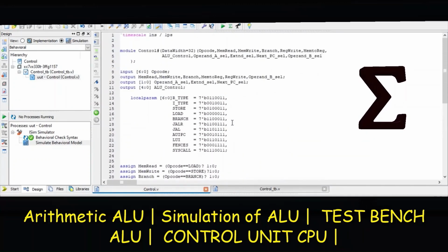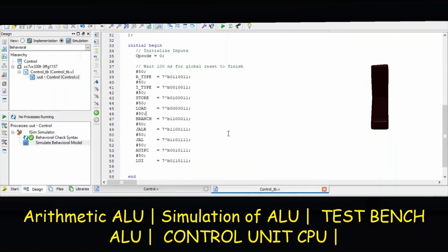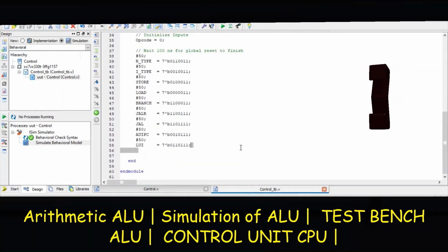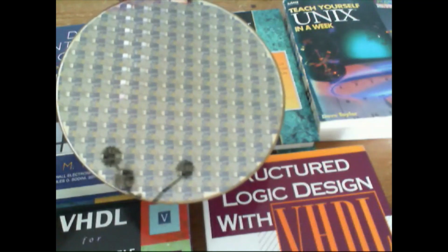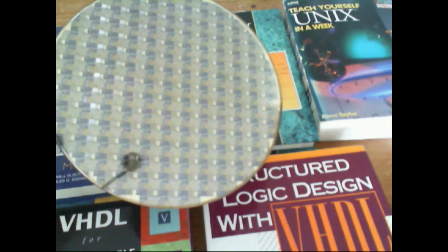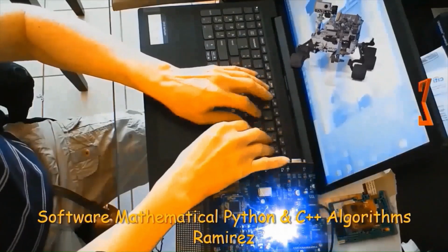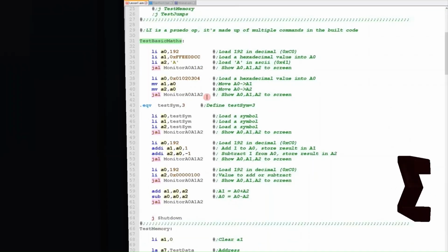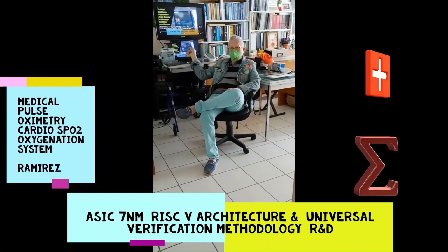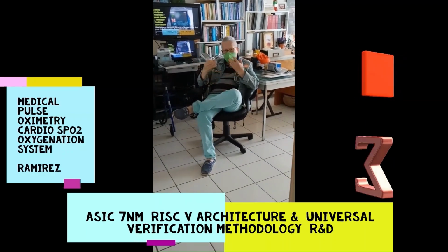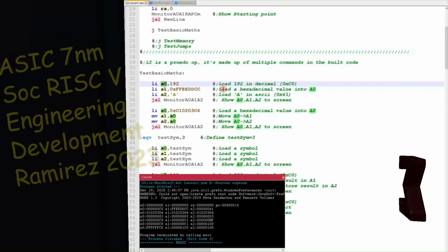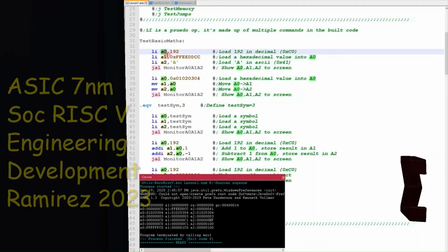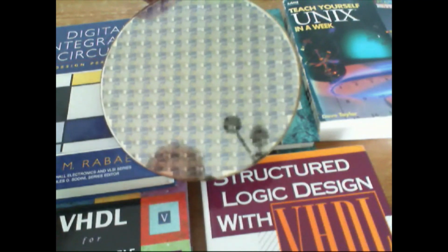At the top level HDL, I successfully determined the configuration and generated the top level HDL design. In parallel, I completed and generated synthesis scripts, synthesized with reference to the library, provided scan insertion, ATPG fault simulation, and also performed the final timing and power analysis.